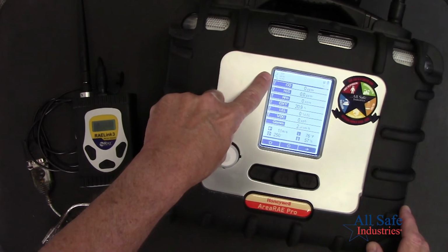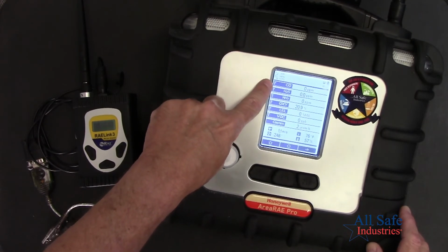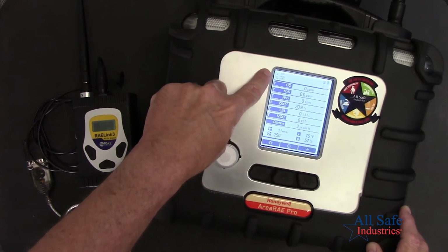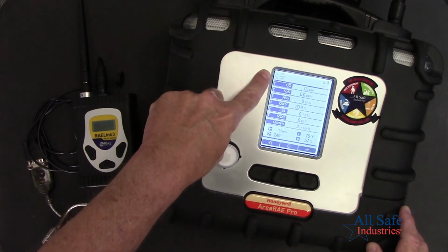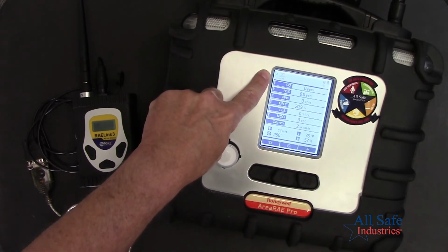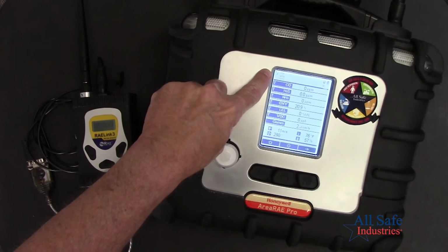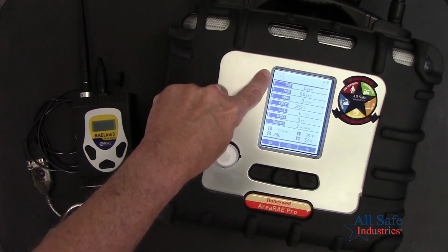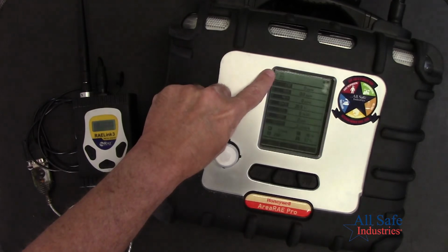If the antenna icon is flashing, like this GPS icon is, that means it's still searching and it has not connected to anything. So make a mental note that that is a troubleshooting step. You want to make sure the antenna icon burns steady. That means it is communicating. If it's flashing, it means it's still searching for something to talk to. So that's your final step.